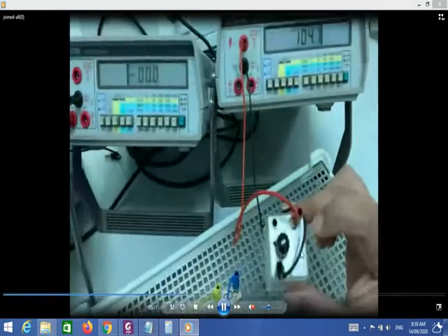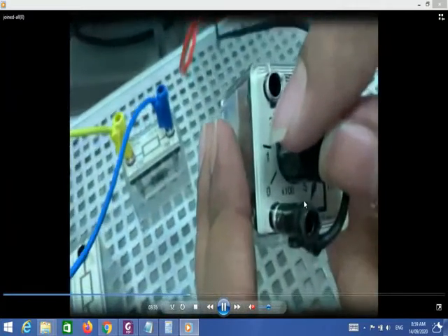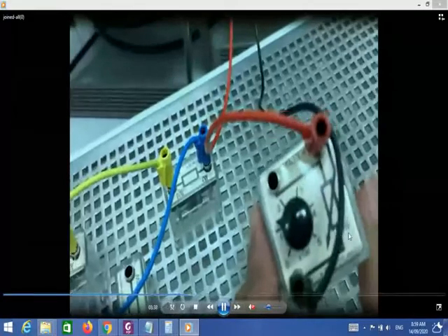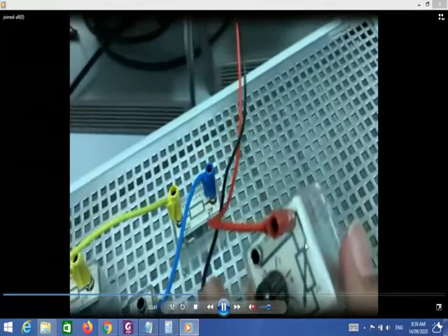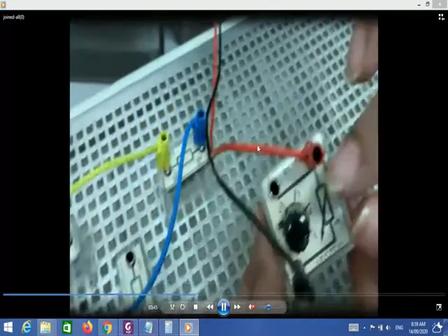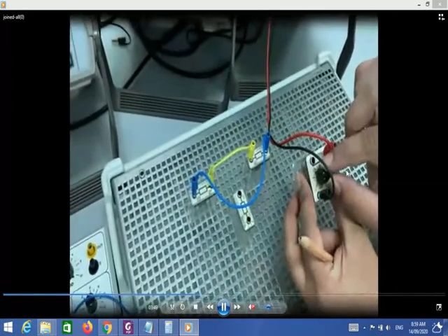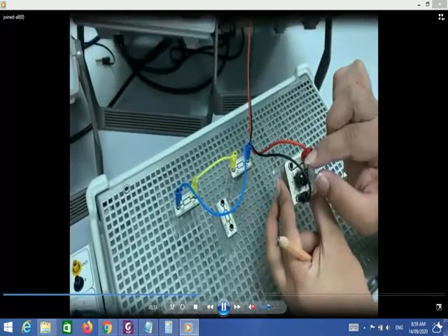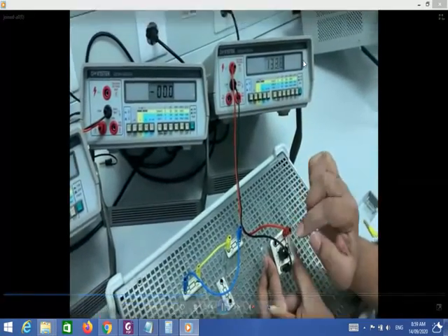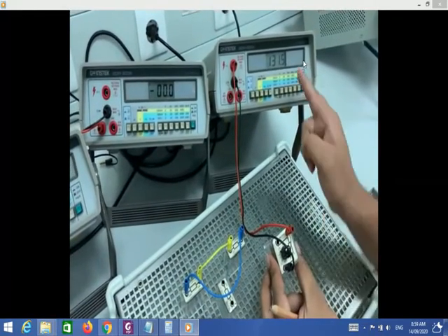This is our potentiometer, which is 470 ohm. Because I need to set 131, which is less than 470, I can use this potentiometer. We'll connect one point at the top right and another at the bottom, and we'll use this knob to set the resistance to 131.4. We should be very careful in doing that. A small touch may make a lot of difference. So let's take approximately 131.5 or 4.